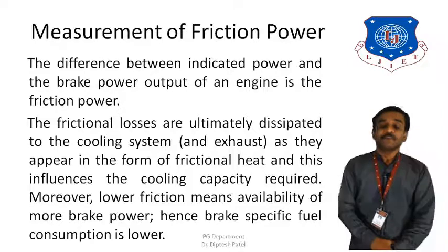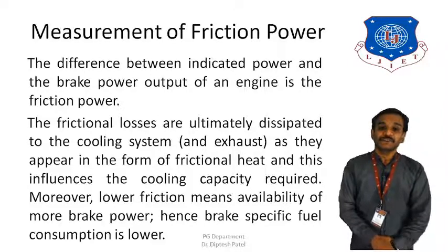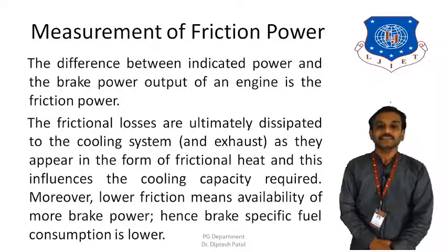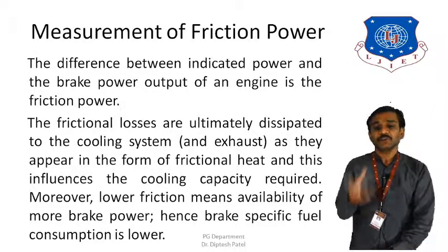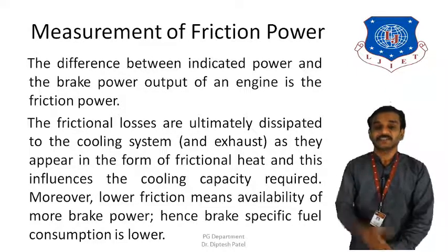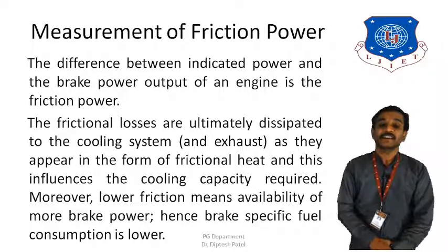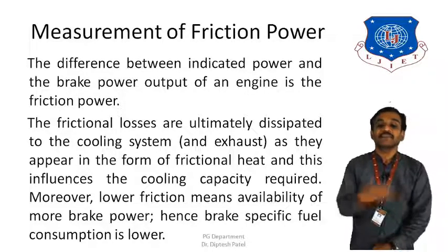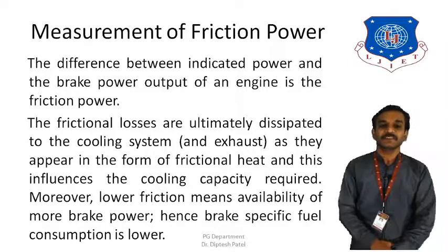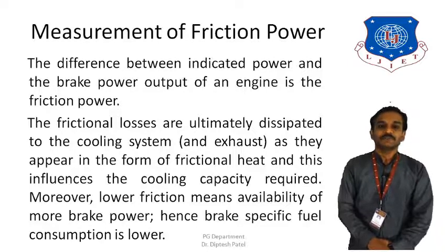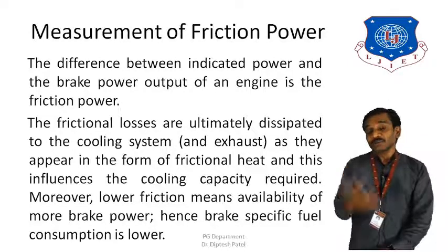The overall aim of an engineer is to reduce the friction power as low as possible. Since we can reduce the friction power, we can enhance the brake power, and therefore the brake specific fuel consumption would also be lower. So this is what the friction power is.